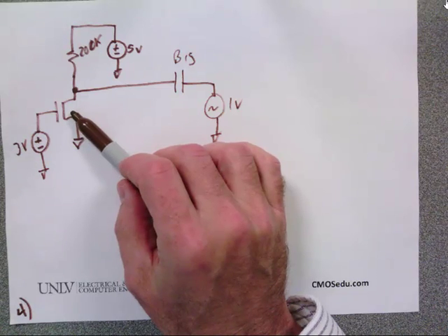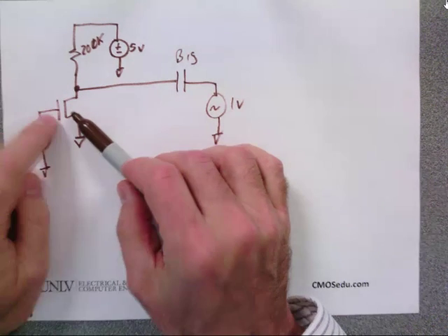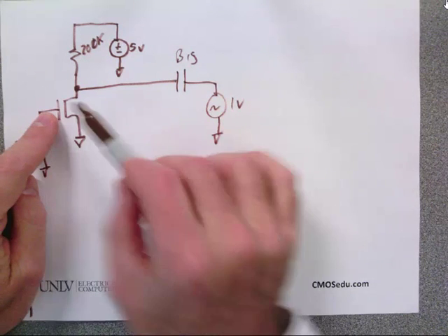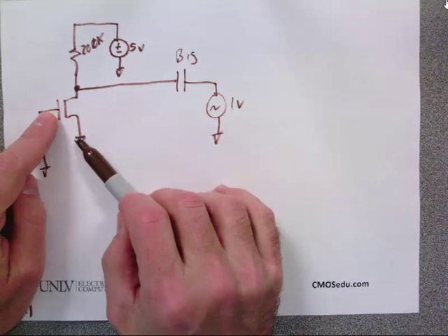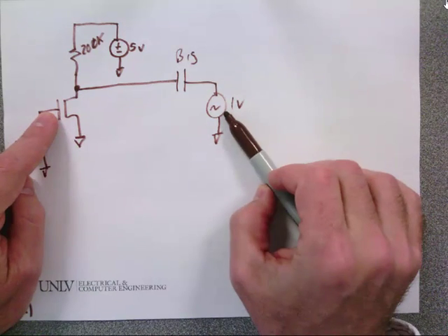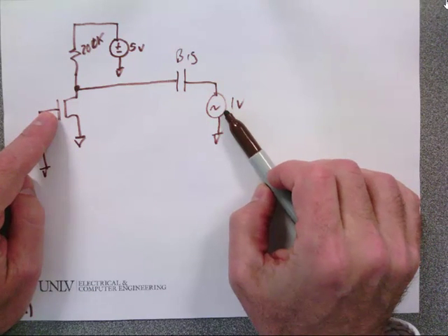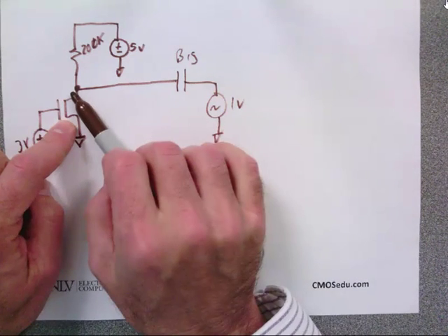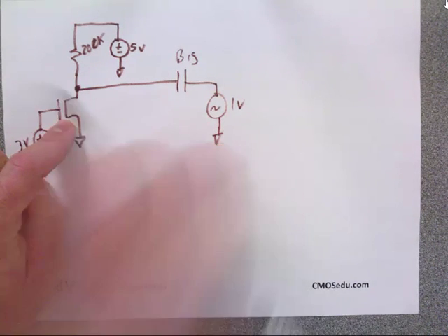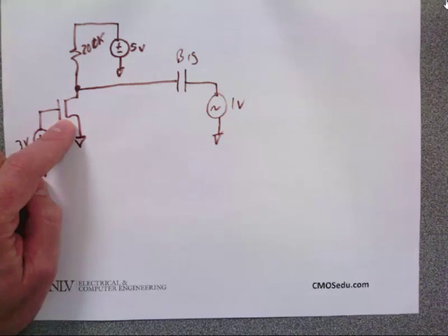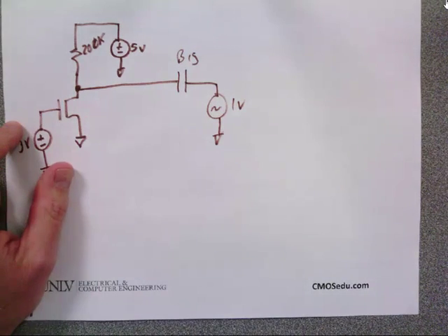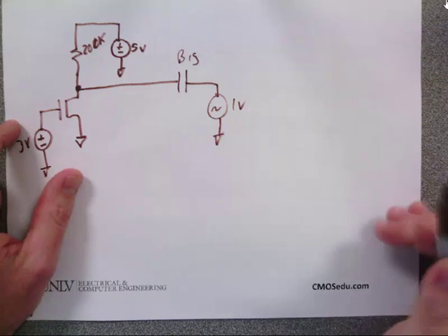Spice doesn't look at the actual amplitudes that you use after you replace the devices with small signal models. So if we calculate the resistance of this device as 1K, and we put 1,000,000 volts in over here, when I do an AC analysis, Spice isn't going to know that 1,000,000 volts will move this into saturation part of the time, because it moves it up on the curve because of VDS. It's still going to assume it's small. Okay, so I'll come back to that in a minute. If you didn't follow that, that's fine.